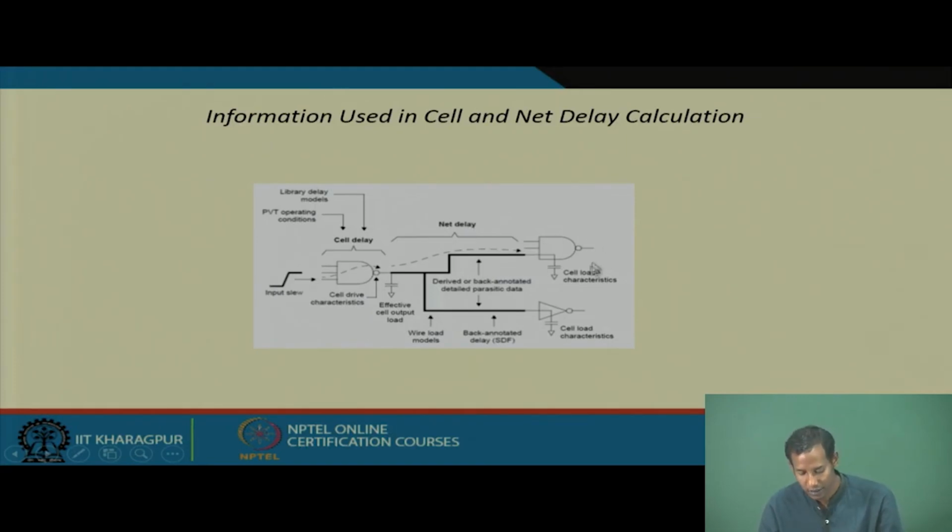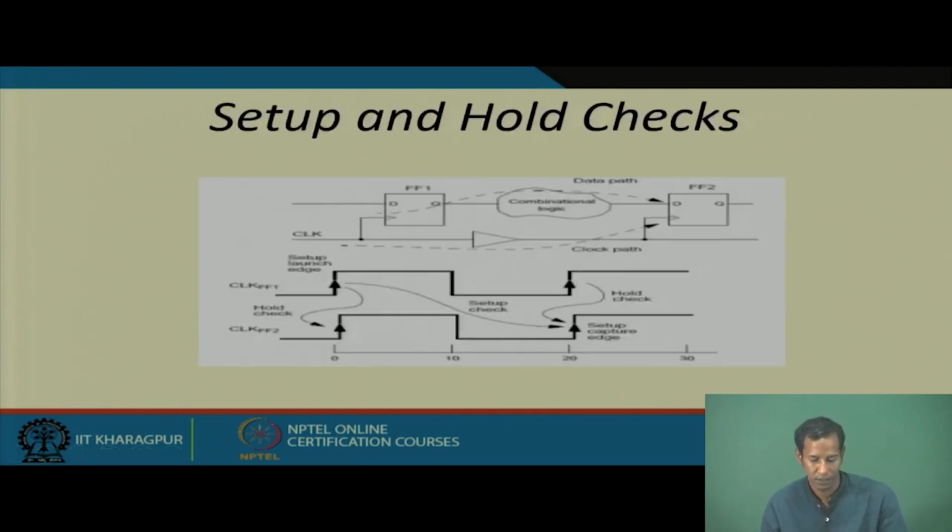Then you can calculate this for each of them. In timing analysis, each of these parts will act as a node, and the intermediate delay information will be assigned as a weight to each edge, and after that it calculates the timing analysis of your full circuit.